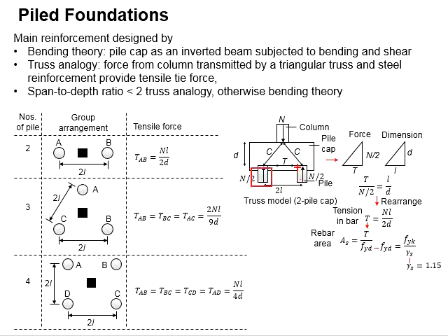These reactions will generate resistance to the axial load, and all these loads are to be taken by the pile caps. Based on the principles of the Truss Analogy, the stress within the pile cap will appear as if a truss, where these two will be in compression while this will be in tension.